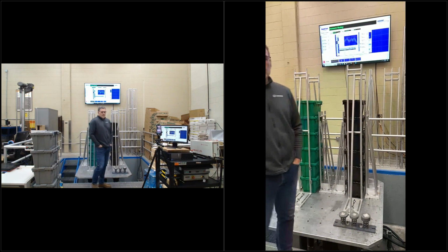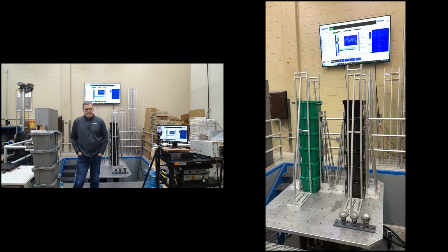A lot of options. What you want is good coupling. If you're going to use accelerometers for drop testing, shock testing, vibration testing, you want it to hold, and you don't want it to impact the, no pun intended, the measurement. Meaning that if you use double back tape, either to attach field data recorders or even accelerometers in the laboratory, the thickness and cushioning characteristic of that tape will change the measurement, because you're going to be measuring the response of the tape, not the response of the widget.